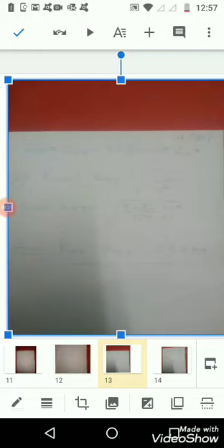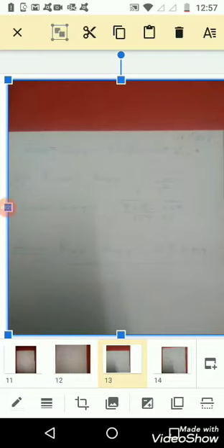Here Kxx is equal to Kyy, which is equal to under root I divided by A. Substituting the values, 8282.042 divided by 179.07, we get Kxx is equal to Kyy is equal to 6.8. Next slide.